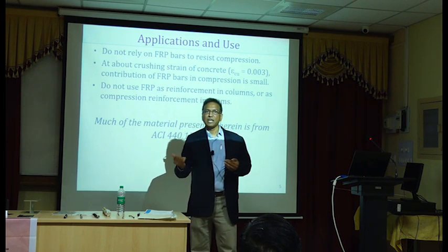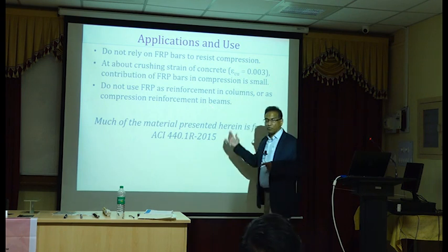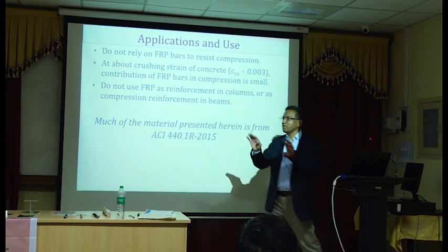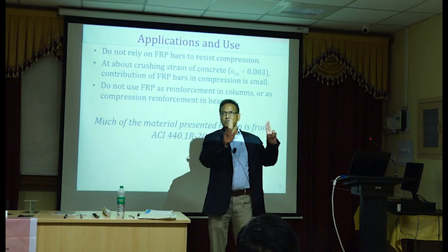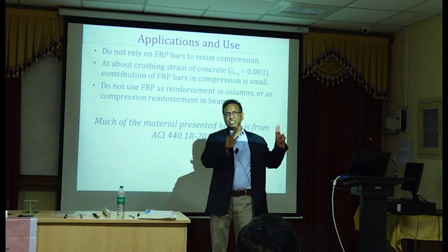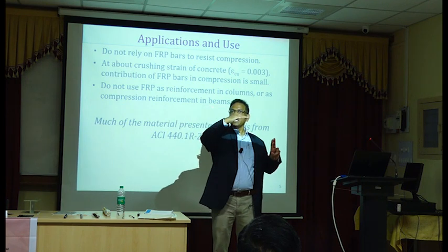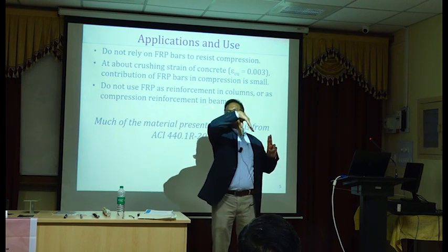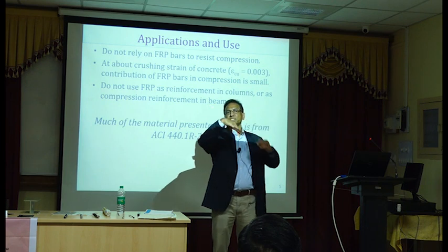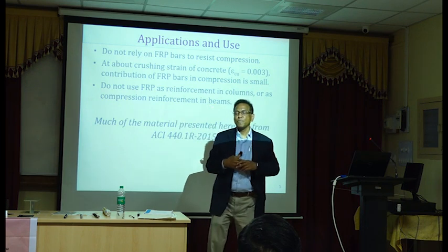They are doing that. That's not disallowed. So you may want to consider those things, because if you have a three-span slab bridge at the support locations, the top is in tension, right? It's bending this way. Top is in tension at the supports for continuous beams.